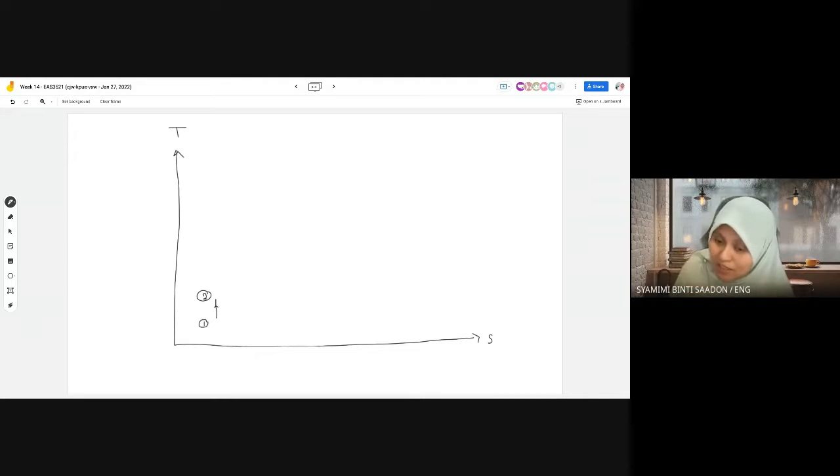Please remember, the diffuser's function is opposite to the nozzle. Nozzle kan kat exit. With the nozzle, we want to increase the velocity of the gas to a high speed gas flow so that we can produce thrust. So diffuser terbalik, opposite. Diffuser is at the beginning. We have a diffuser to decelerate, to slow down, because we want to capture the air intake so that the air can enter our compressor in the core engine. So we start with the diffuser. So 1 to 2 is the diffuser.